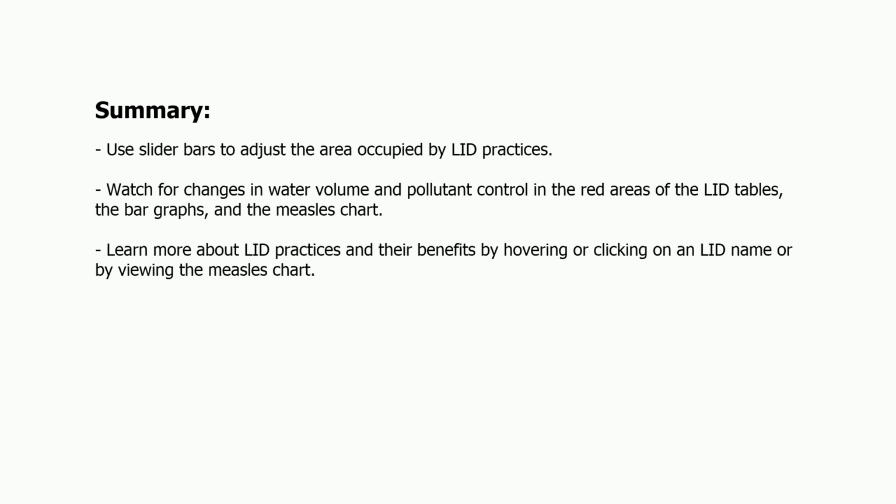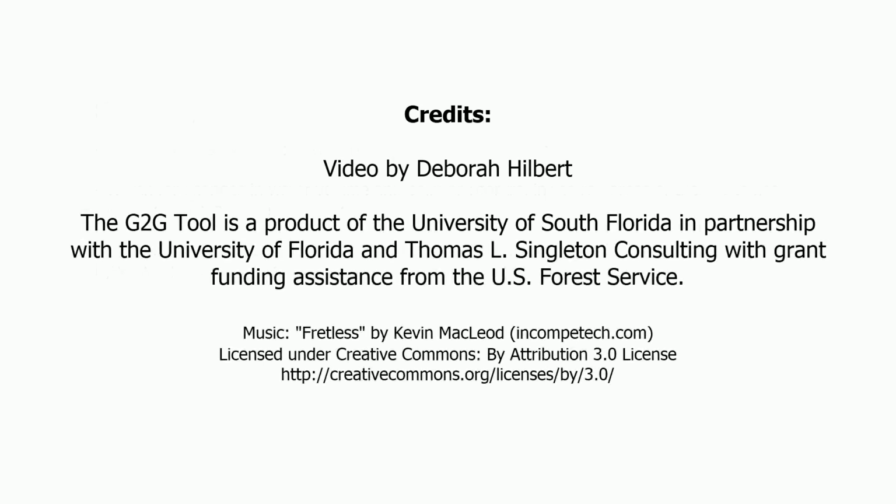Make sure to check out the user guide for more information on the process of selecting LID practices, because there's some really good descriptions of how to use best management practices and adaptive management to really select the right LID practices that are most practical but also complement each other. Again, you want to treat stormwater not as a nuisance, but as a resource.